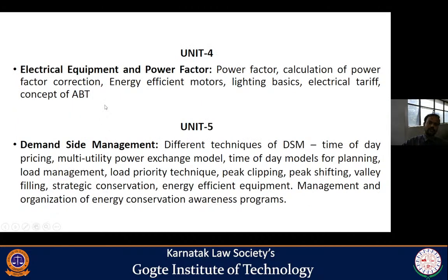And the next one is electrical equipment and power factor. In most of the industries, the induction motor is used, the 3-phase induction motor. So this is very important, to improve the power factor of the motor, because it is the main motor used in most of the processing industries. Okay, so we always have to improve it, since your induction motor will be running at low power factor.